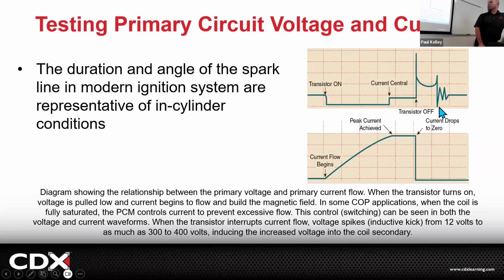Do you see this shape right here? This is measuring voltage. We'll just start with this. The voltage was here, and it was going along, right? The more right we go, this is time. This is voltage. This is the oscilloscope screen. Cool. So the voltage was fairly high. We turn on the transistor. What does that mean? That means we just connected it to ground.